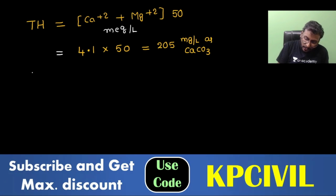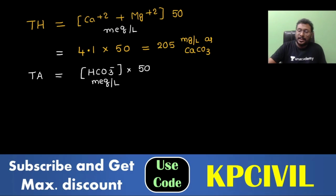What is then total alkalinity? Total alkalinity is equal to, from the given ions, bicarbonates in milli equivalent per liter into 50, because carbonates are not provided.